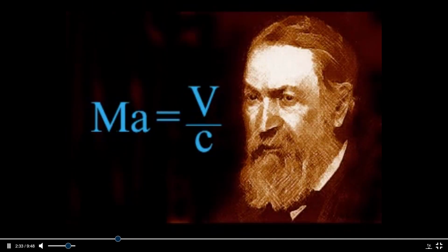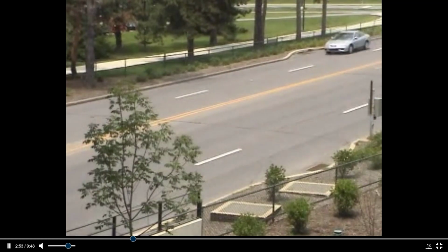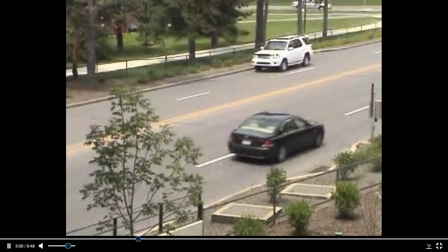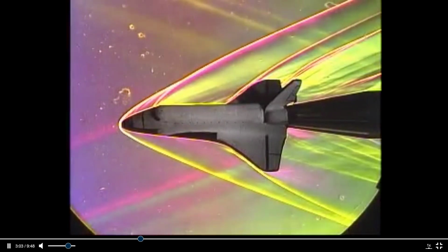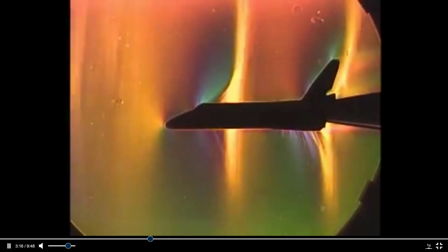Another very important non-dimensional parameter is the Mach number, named for Austrian physicist Ernst Mach. It's defined as the ratio of the speed of a flow, v, to the speed of sound, c, and it determines a flow's compressibility. For example, cars usually travel at speeds less than 1/10 the speed of sound, where we ignore any small density changes and consider the flow to be incompressible. On the other hand, some flight vehicles break the so-called sound barrier and fly at supersonic speeds, or Mach number greater than 1. When the Mach number is around 1, as in this transonic wind tunnel test of a space shuttle model, small speed changes make a big difference in the flow pattern.